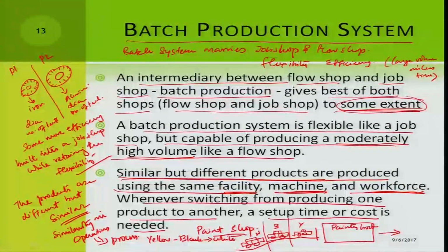This is the painting sequence. Whereas, if it had been white, yellow and black, you would have had much lesser setup time, because flushing the nozzles after black paint to a white paint is quite time consuming compared to flushing from yellow to black or white to yellow. So, it is usually better to paint from a lighter color to a darker color.